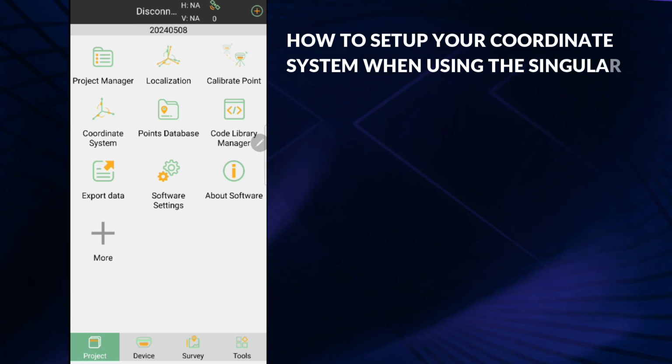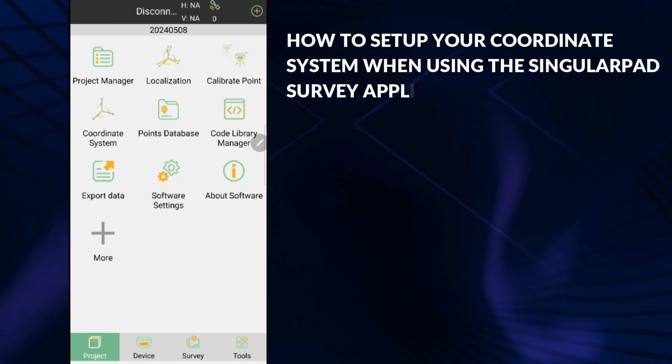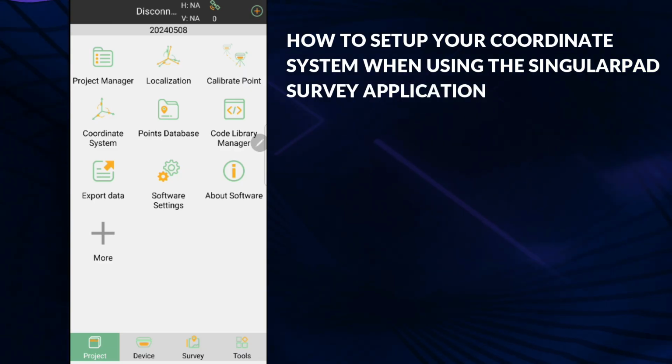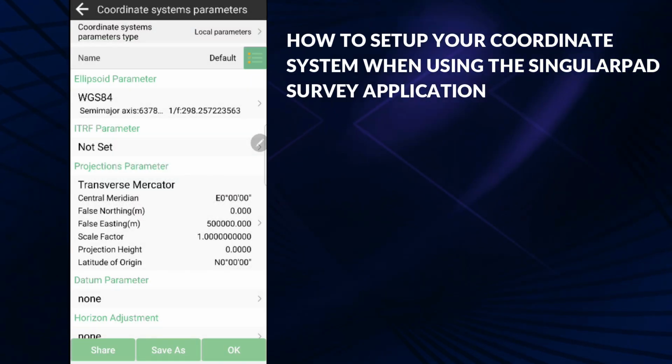GNSS receivers. So to create a coordinate system, we are going to go to the project page, which is the first page, and we'll click on our coordinate system icons. So select coordinate system, and we're going to check if the coordinate system parameters type is on local parameters. So we'll leave that at local parameters.